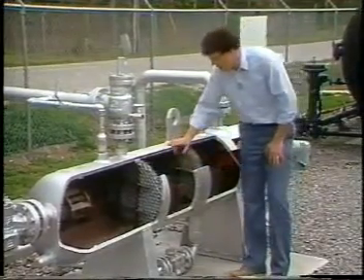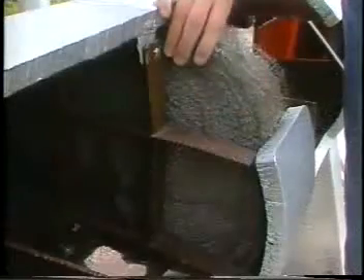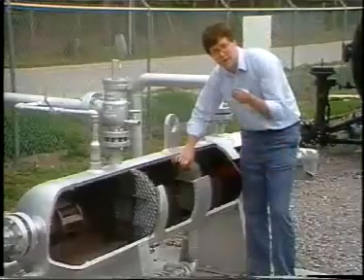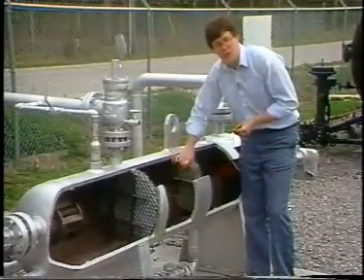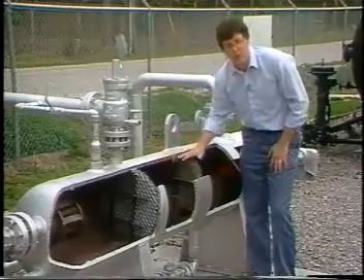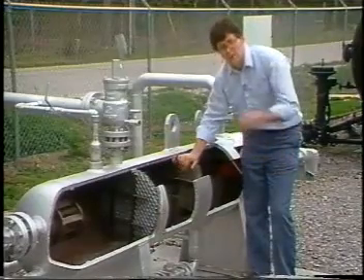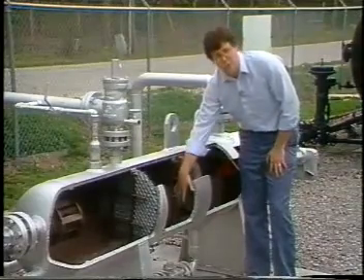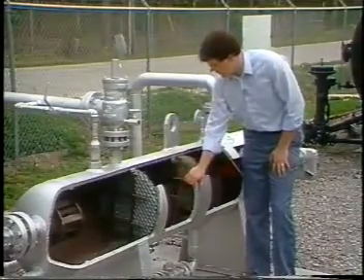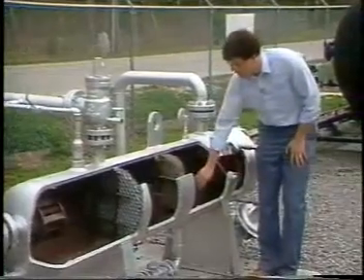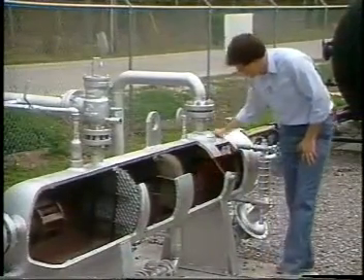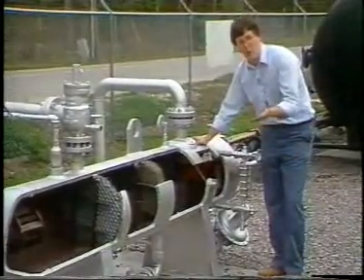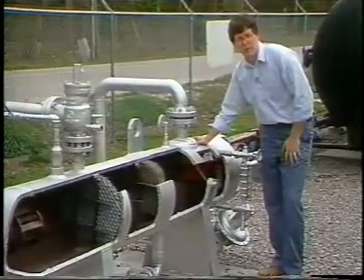In this particular separator, we next see a wire mesh mist extractor. The wire mesh mist extractor coalesces any tiny droplets of liquid that may still be entrained in the gas that's flowing horizontally at the top of the separator, and coalescing these liquid droplets allows them to fall down to the bottom and re-enter the liquid phase at the bottom of the separator. Here we have another wave breaker, and finally we get to the end of the separator that's responsible for the separate dumping of the oil and water phases after they've been separated.